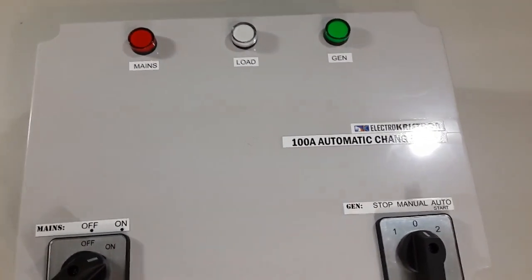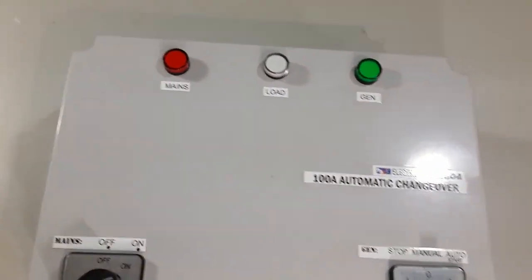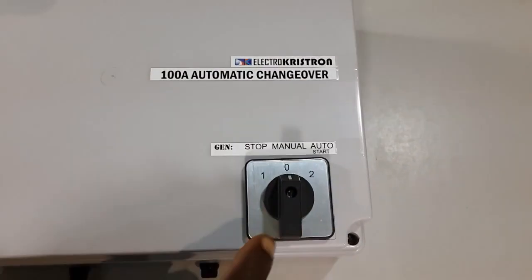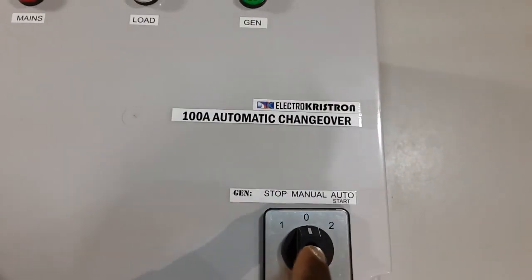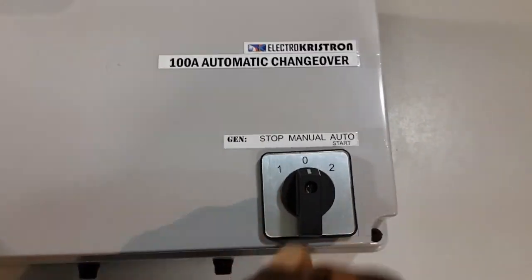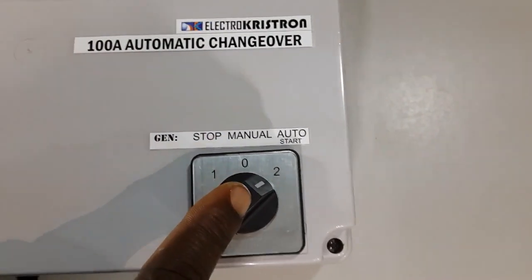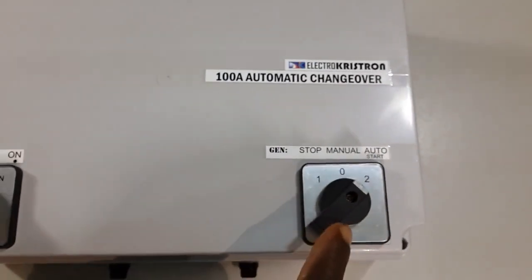Alright, now the second function, which is different from the automatic changing over function, has to do with the control of your generator, the ignition of your generator per se. Now what that means is that if you decide to have your gen start automatically as soon as power fails, then putting this switch in the AutoStart position will allow your generator to start automatically as soon as public power fails.